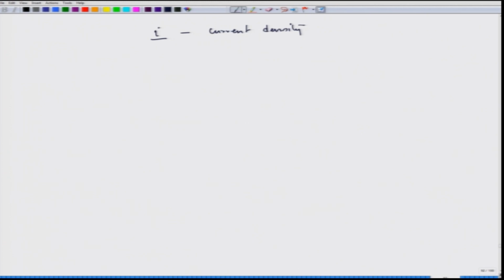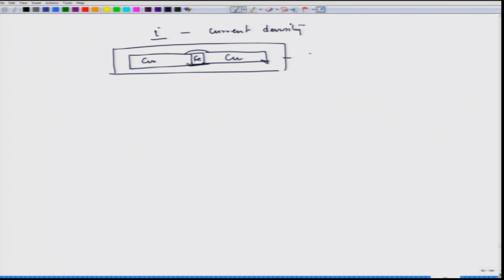If we recall, we saw that in case of galvanic corrosion, if we have a copper plate, and another copper plate, and a kind of iron rivet which is connecting these two copper plates, and we put it in NaCl solution, then according to the galvanic corrosion, the rivet will dissolve quickly and finally lose its joint strength.